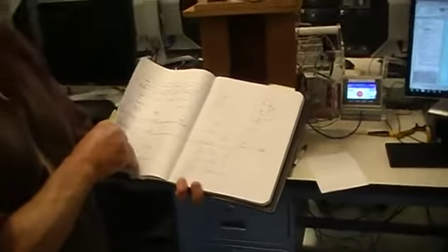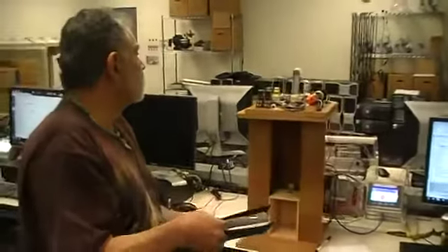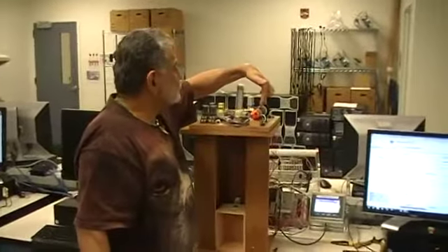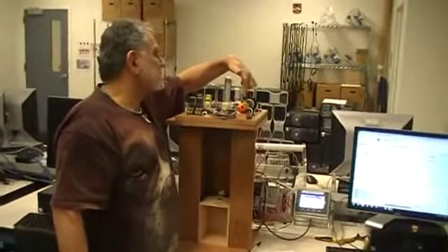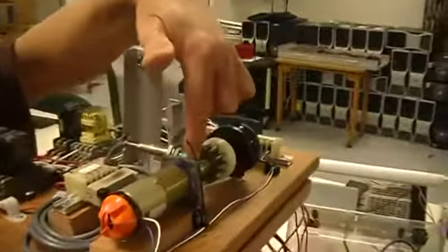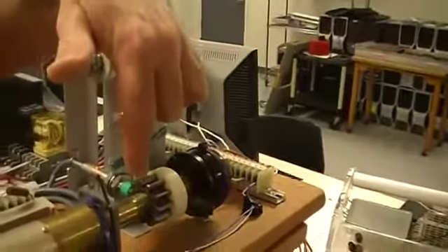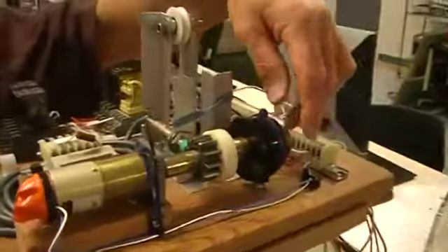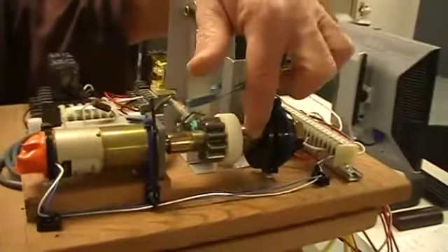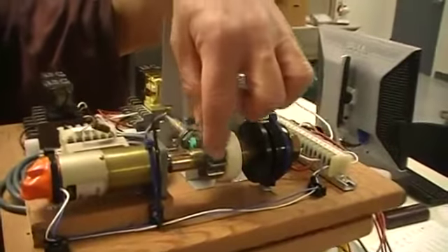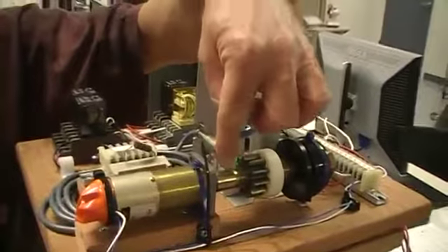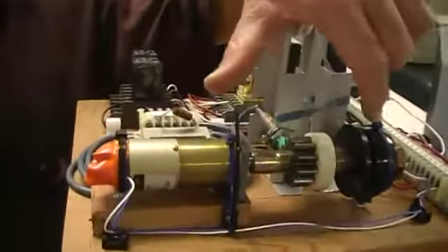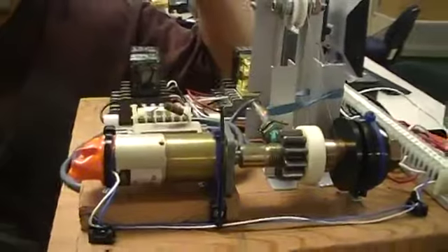Good question. The coupler you have on your motor, can you explain that a little bit more? Yeah, what happened was this motor had a shaft, so the center of a bolt got drilled out to match the threads of this sprocket. I added a bolt back here and squeezed them together to get the pulley tight, and then I tightened the whole thing so it butts up against the other bolt so it can all be one piece. Very cool.